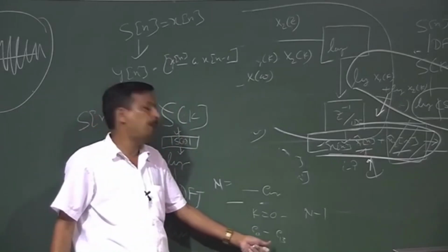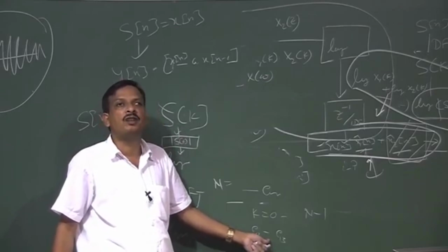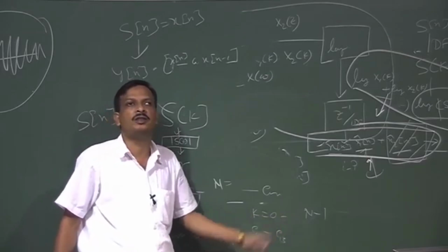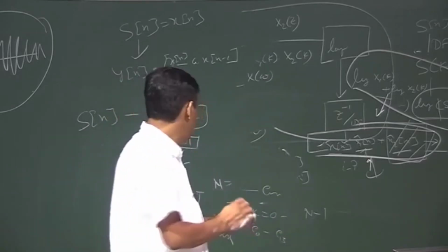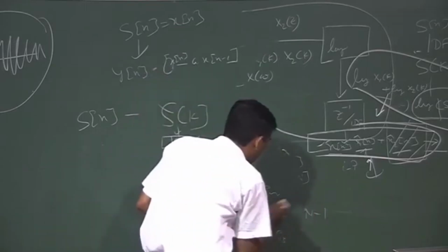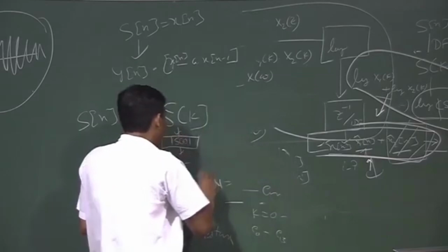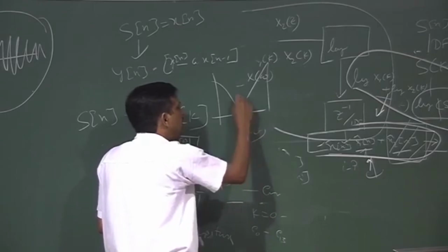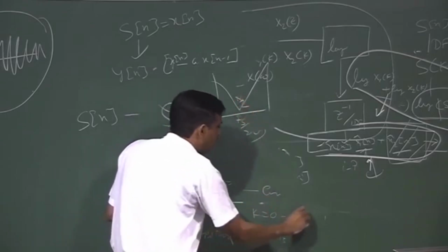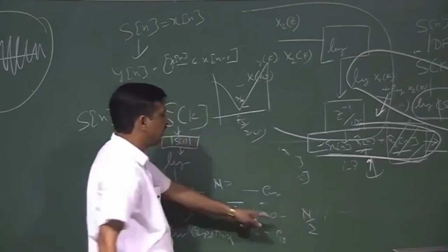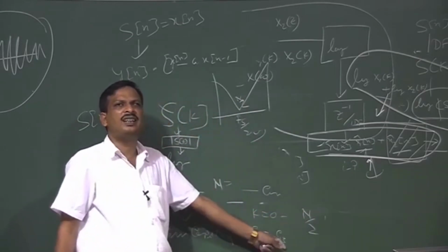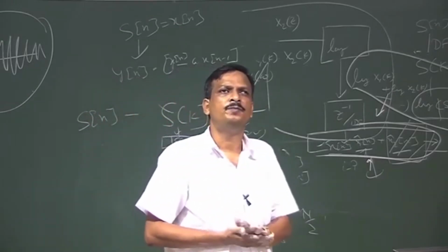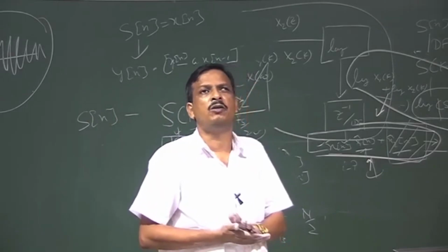Those are called the spectral coefficients. Basically this is done up to N by 2, because k equal to N minus 1 is not required, since DFT analysis has the symmetry property. This is Fs by 2, which is N by 2, so k equal to 0 to N by 2 is sufficient. I take some length which represents the envelope, the spectral coefficients. This is the extraction of the spectral coefficients.